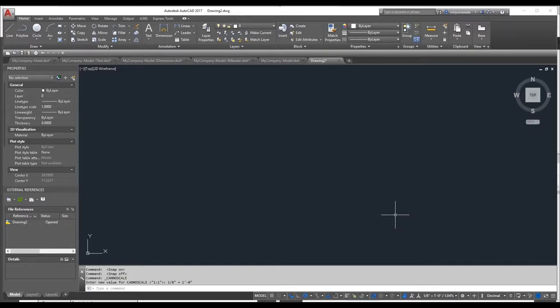One more setting that I don't know if it is in the dialogs or anything is called XREF override. This is a brand new setting, I think in 2016, where if you set it to 1, it will nullify any overrides that a person has in the base XREF file. So if you're getting a consultant file, and you want to override them to a color and a line weight you want, you can set that variable to 1, and then all their settings will be nullified.